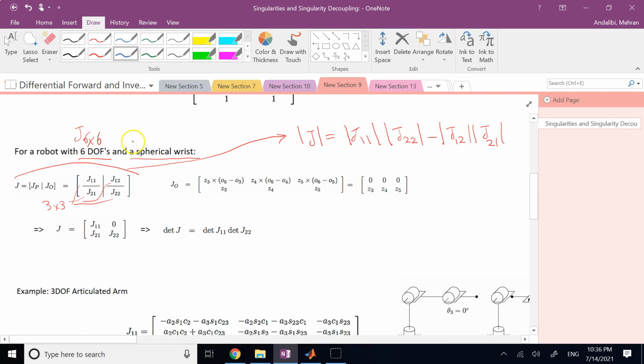So with the spherical wrist, I can say that O3 is the same as O4, is the same as O5, and if I neglect the small distance between this wrist point and the center of the end effector, I can say also this is equal to O6. So this last one depends on whether I can neglect that or not. If that is the case, it means these vectors here, all of them are 0. But what were those vectors, if you remember?